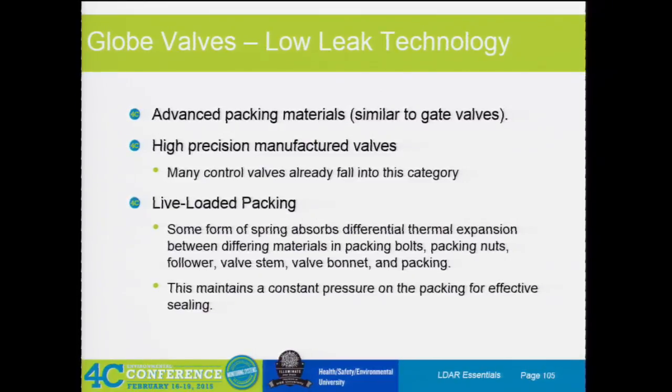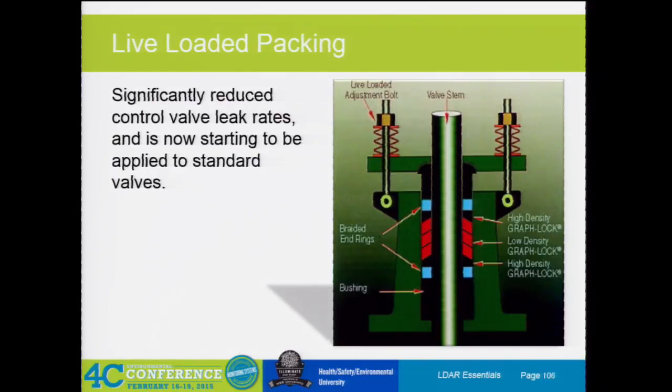Again, things that have helped this type of valve, you got your packing again, better manufacturers. Many control valves already fall into this, and then your live loading packing that we've already talked about. And I guess there it is, the way Bronson explained it, some sort of spring or something to absorb that. Usually you'll see that in the form of a stack of washers.